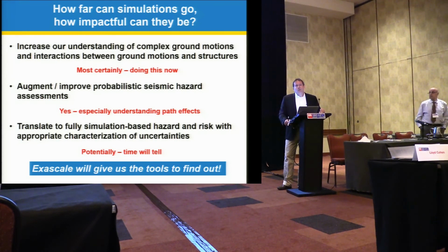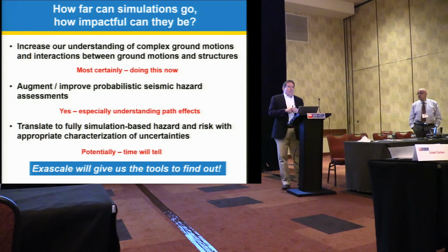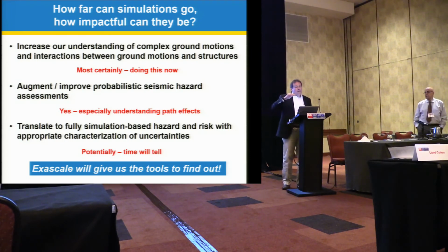No, so we will do both. You certainly want to understand the regional variation of risk for that structure. Let me just give you an example of why. So the Hayward Fault is here. Traditional probabilistic risk assessments assume all locations that are equidistant from that fault have an equal hazard.